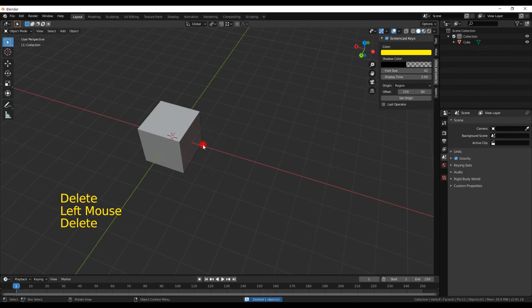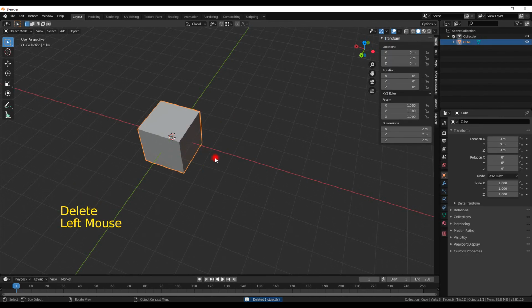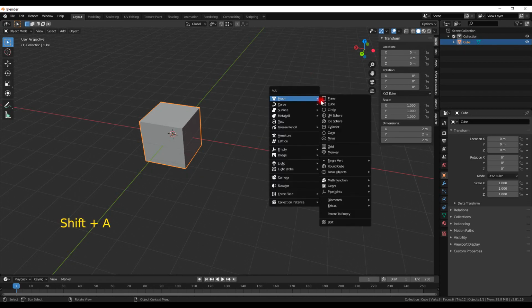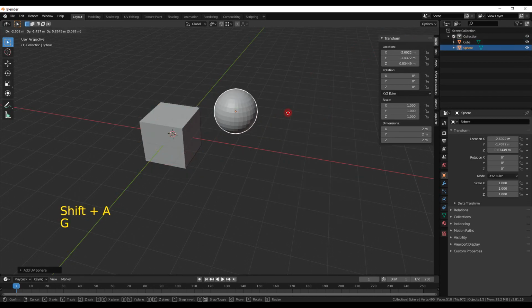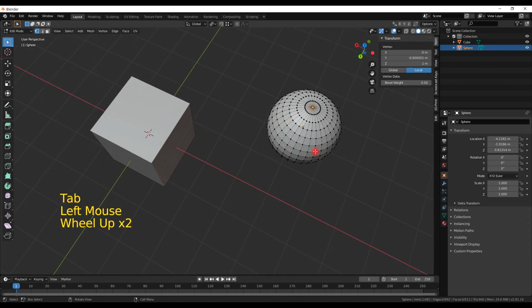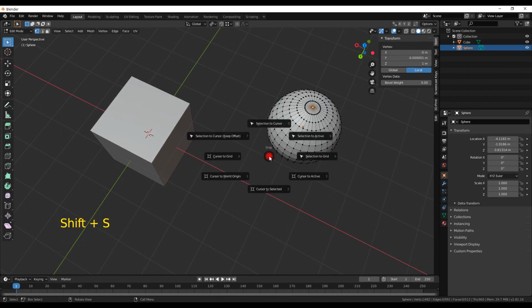This is also very important that you know the quick menu for this, which is Shift S. Here you have many types of snapping. First of all, you can snap the cursor to whatever you have selected. So if I have a ball in here, and in the ball I have the top vertex here, I can now with Shift S say snap cursor to selected.